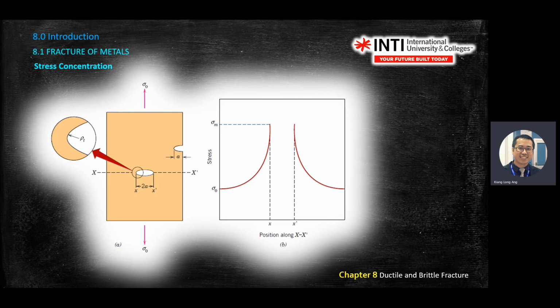Just now the cavity was very small, but if you enlarge the cavity, you get a bubble form. For the bubble, we only look at half of the A, or half of the length. So this one is the cross section of X. And then you see this is the tensile loading, tensile test, pulling both ends up and down. So we are talking about fracture. For ductile material, you pull both ends, the propagation will be 90 degrees, or perpendicular to the force, or perpendicular to the stress.